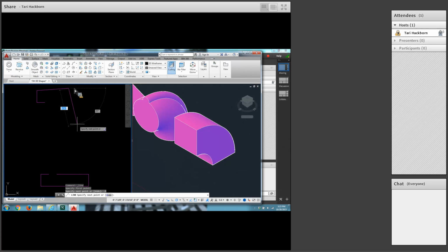or draw a 1/2 inch and come down 3/16, right? Ooh, that was the wrong direction. I can always right click and undo that. Okay, pull straight. Down 3/16. All right. Ah, good. From there, I can just connect to this right here. That's one good part. Tracking up from this corner, I just need a line. It's just going to be my line that I revolve around.